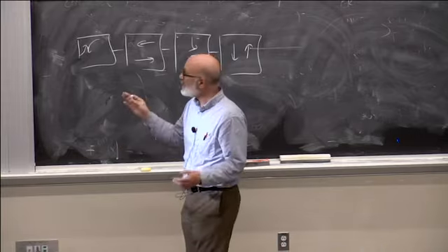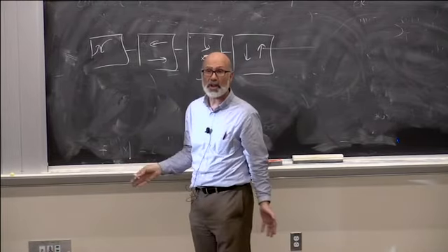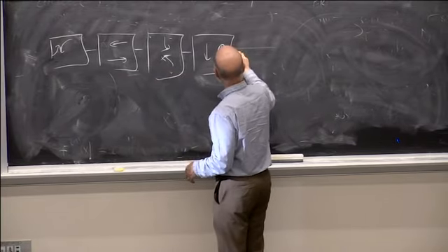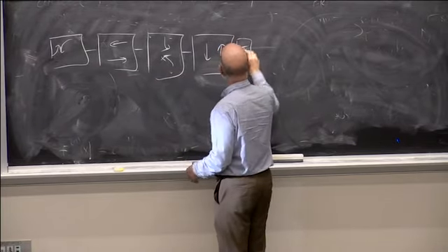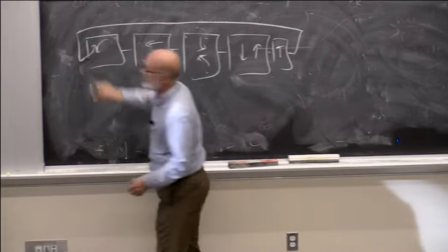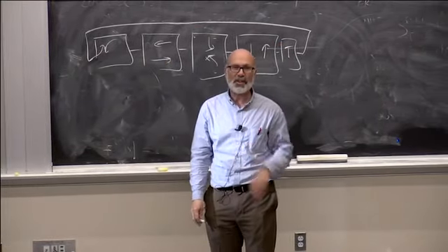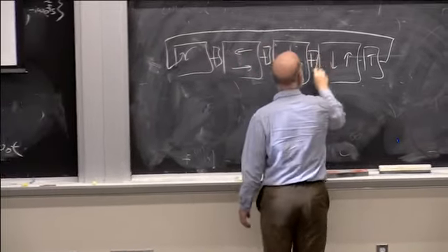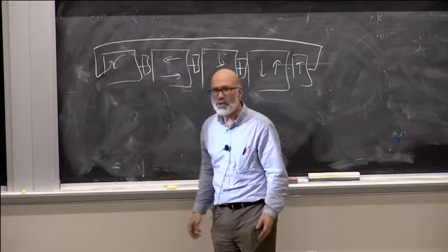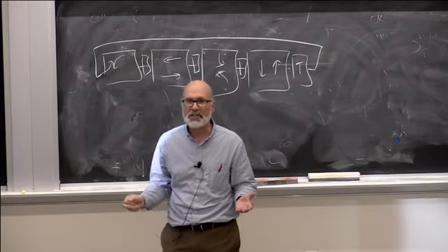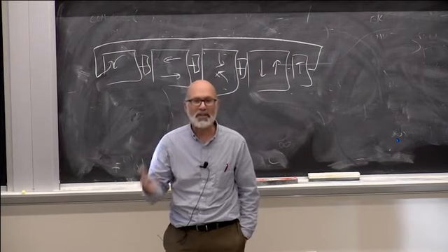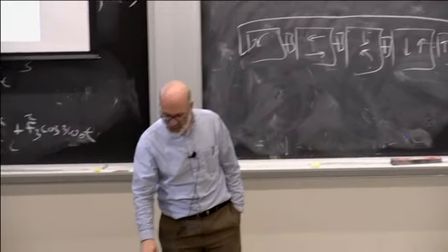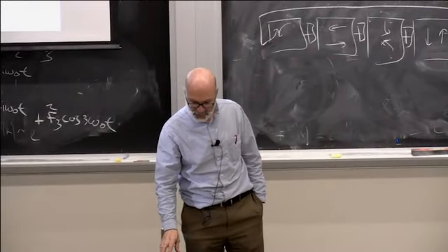And the tram, in this case, because it actually conflicts with all of them. So the normal thinking of a traffic engineer would be, okay, and then we'll have a tram phase here. And now that's the cycle. But the Delft thinking is, we'll put a tram phase here, we'll put a tram phase here, we'll put a tram phase here, and a tram phase here. And if there's no tram, well, we skip it. And if there is a tram, then the tram gets to go. So the tram never has to wait long. So that's part of the, if we can get a man on the moon, we can turn the light green.